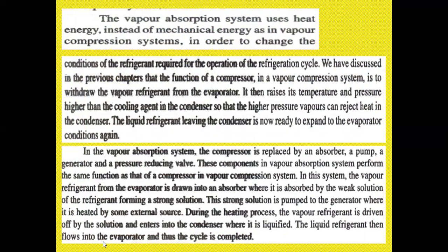the refrigeration cycle. So it raises its temperature and pressure higher than the cooling agent in the condenser, so that the higher pressure vapors can reject heat in the condenser. So the liquid refrigerant leaving the condenser is now ready to expand to the evaporator conditions again.